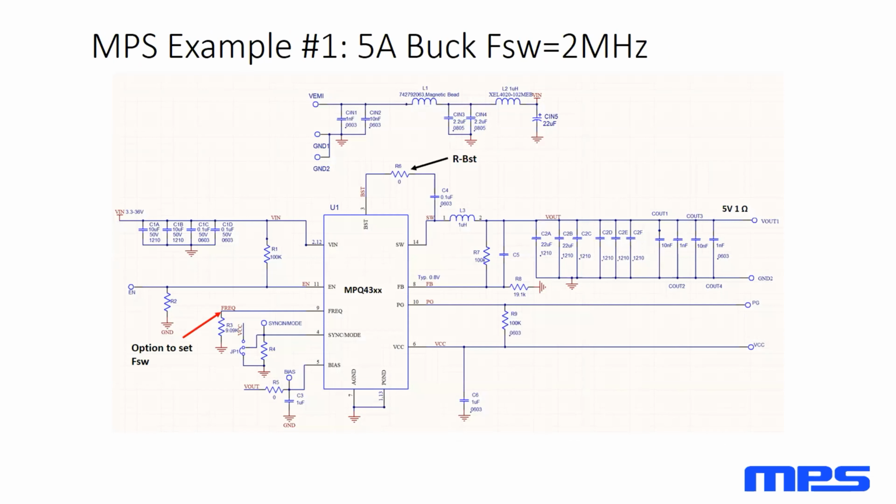Yeah, that will depend device to device. I would say in general, I wouldn't go any higher than 20 ohms, but it's always best to test in your given application. 20 would be a general rule of thumb. I've actually seen applications where we've gone as high as I think it was 40.